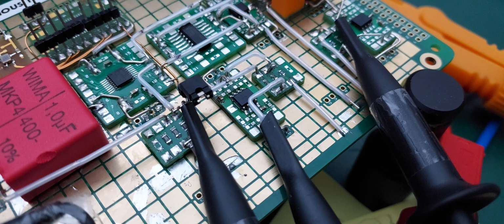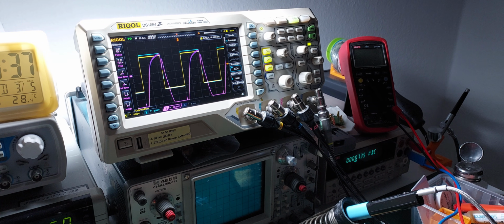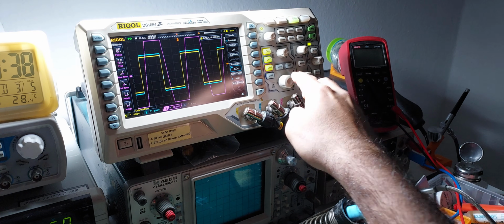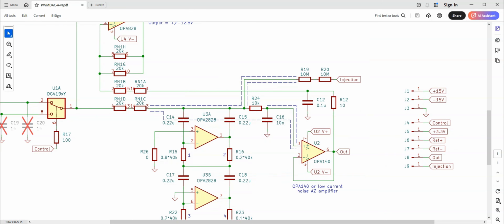ripple for linearity. The trade-off is disproportional in terms of ripple. Connecting the compensation circuit seems to increase ripple drastically. One possible cause might be the output ripple being amplified by the compensation amplifier, which is directly connected to the filter's output. During his experiments, Mark cleverly sidestepped both this and the pre-filter linearity issue by using a post filter and a buffer, and the input to the compensation amplifier is filtered again.